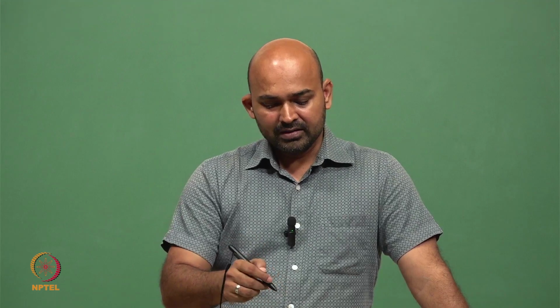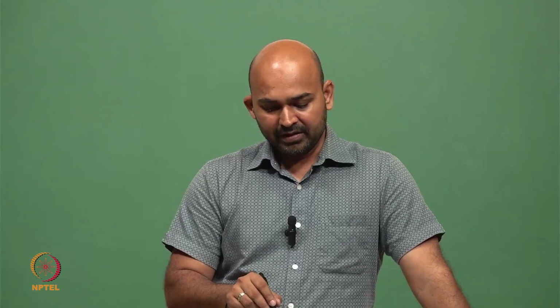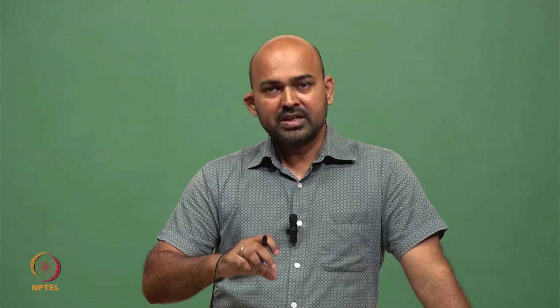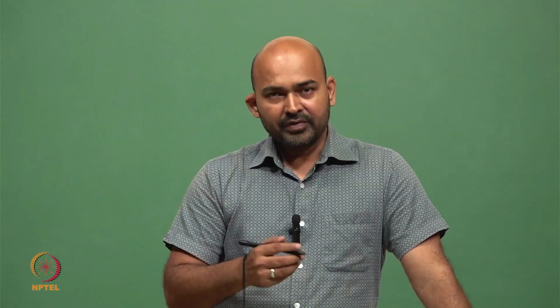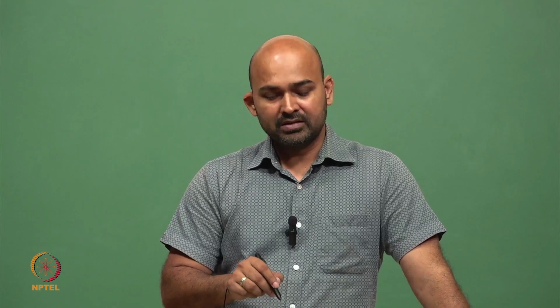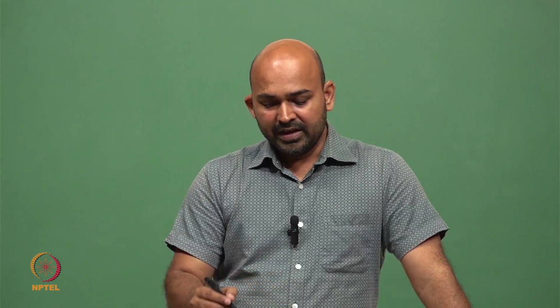taken at the collector end, and the collector has a resistance RC, and at the emitter we have an emitter resistance which is needed for stability purposes. And because stability is needed only for the DC condition, for AC, or when we are talking about the signal, it should not be there. So we connect a parallel capacitance CE, which bypasses this emitter resistance in case of the signal analysis, and we get the boosted output at the Vout.